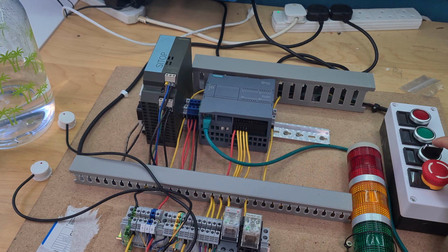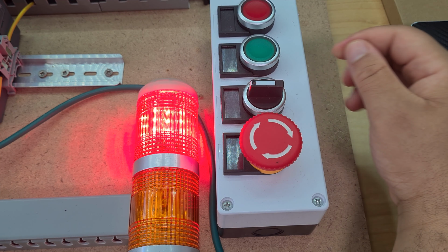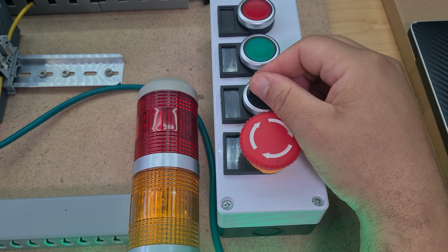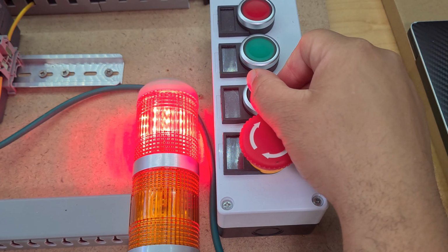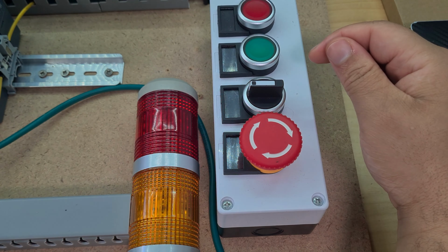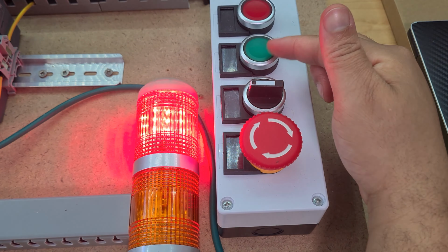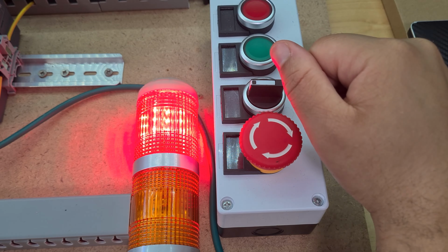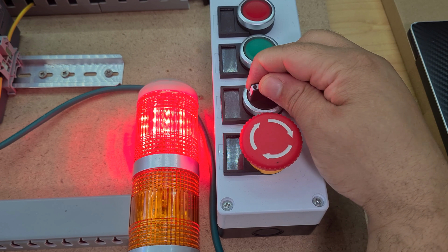I've set it so that this two-position switch over here will reset it by doing that. But the really clever thing about it is that if you reset it too slowly, it won't reset. So I'm in error now, and if I go to switch it like that, it hasn't reset yet. If I don't switch that back within 2 seconds, up there and down there, it doesn't reset. So that will reset it. E-stop will also likewise require a reset to work.